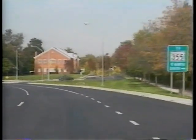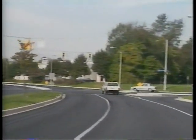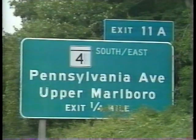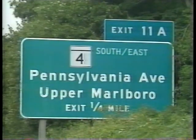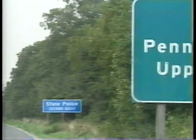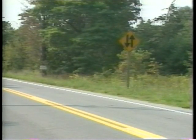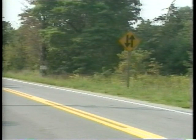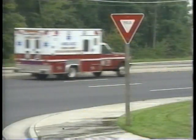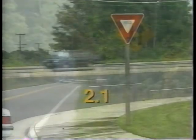In this program, we have covered the placement and location of signs in 3 areas: urban, rural, and freeways. If a sign is legible and located properly, a driver traveling at normal speed will have adequate time to make a proper response. Sign height practice. Sign height in rural areas is usually 1.5 meters. Urban and freeway signs should be higher, about 2.1 meters.